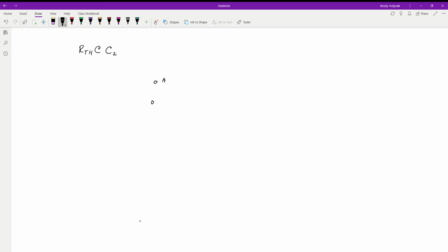So we're going to start over here. We've got A and B. This part's going to ground. This was C2 that we took out. So it comes in, and we know for sure that it's in parallel with R3. R2 comes down and around because it's also connected. So VDC is a short, so that's connected to there. Then we come into here, and then we come down.